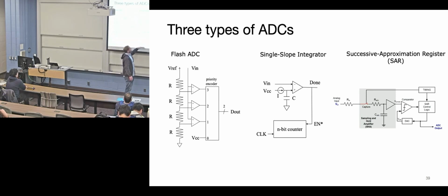Slope integrators, whether they're dual slope or single slope, doesn't really matter. They're based on taking an analog value and using time to count out how long the reference voltage goes until it meets the input voltage. So that's an important concept.